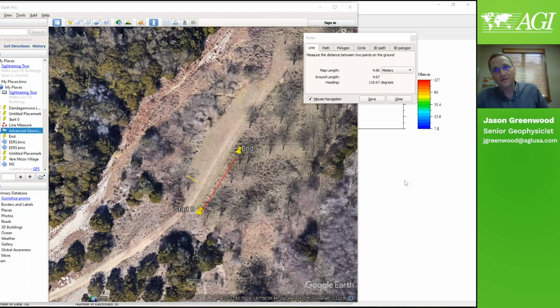The issue of running alongside roads is that they're common places for utilities, pipelines, and conduits, and those are the concern. It's not so much the road. The road would have a very minimal effect. That rebar that's in the concrete road would have very minimal effect if you're running parallel to it, or if you're running through it, as long as you avoid directly touching the metal. There are case histories that show good ground truth correlation when they're measuring through reinforced concrete in a thin layer at the surface, as you would have in a road.